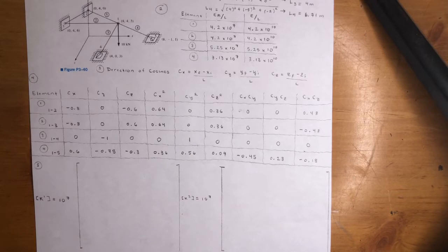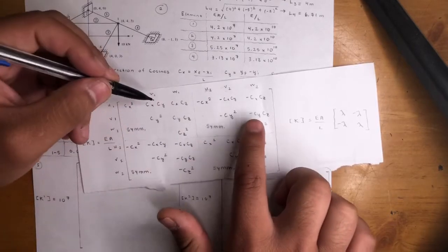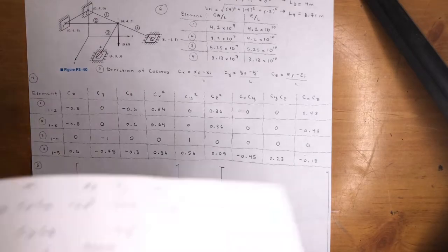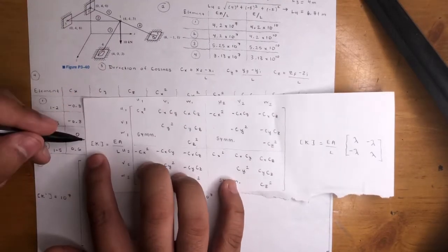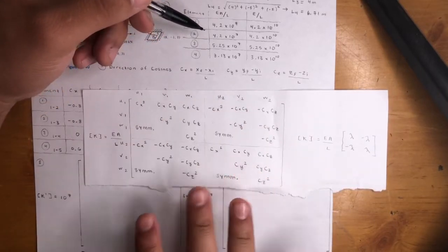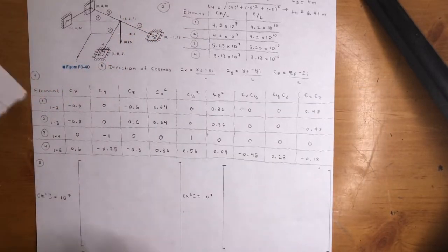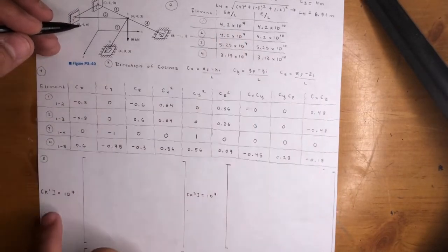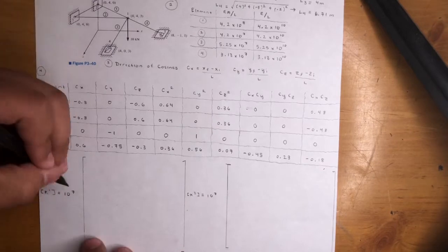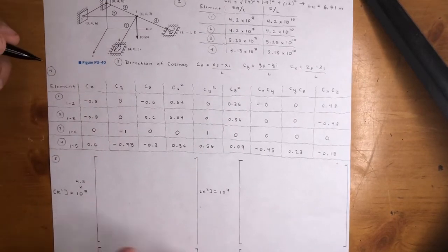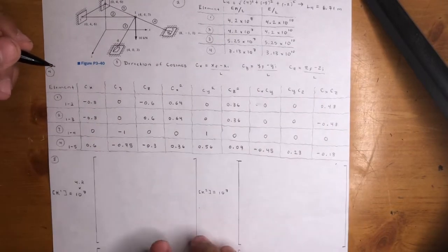Now we're gonna go ahead and start doing the stiffness matrices, right? Remember, I told you we will want this 6x6 matrix for each element. That's exactly what we're gonna do. So the formula is K is equal to the stiffness, EA over L, that we got here, times the matrix. Now, we'll get there, hold on. So for the first one, K1, that is element 1, it's 4.2 times 10 to the 7. They're all 10 to the 7, so I just already threw them in there.